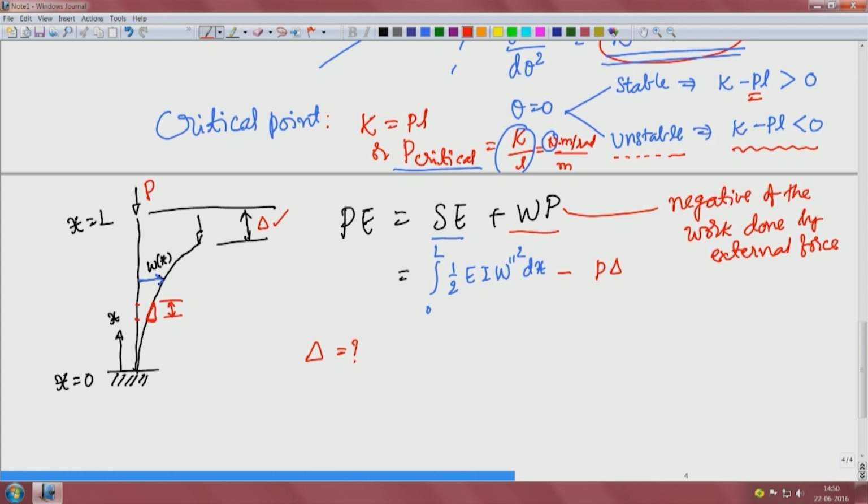Okay. Let me blow it up, let me draw a larger one like that. This is dx, which was what was here, which has come here. And what is this? That is the incremental transverse displacement w. So, Pythagoras tells us that this one, if I call that dy, what we want, that height, is dx square minus dw square. Let me just write square root of dx square minus dw square.